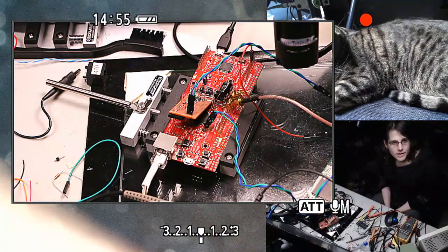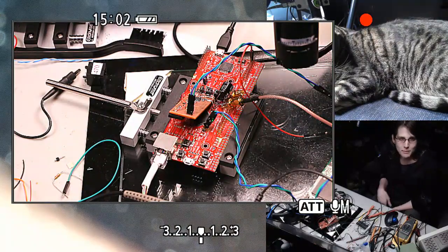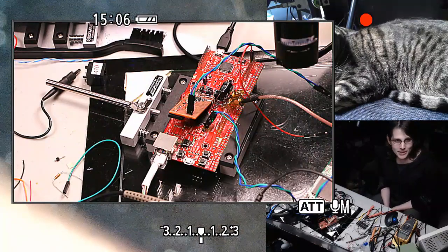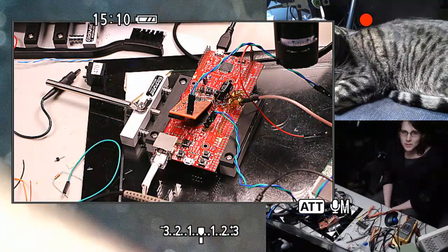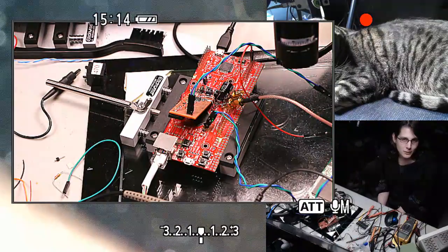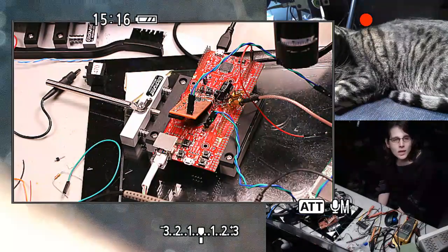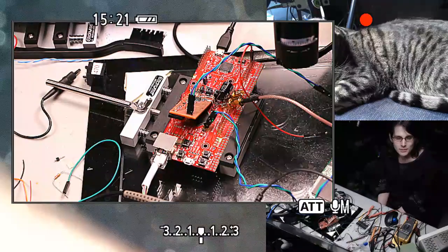And that's a little tricky because I can't just stick it on USB, because if I'm underclocking that whole chip to try to replicate this situation, then I would also end up underclocking the USB interface, probably in a way that it doesn't support very well. Maybe the on-chip clocks are programmable enough that I can make something work, assuming I control the firmware in this case. But it might be easiest just to still bridge it back to a Raspberry Pi or something like that over SPI.